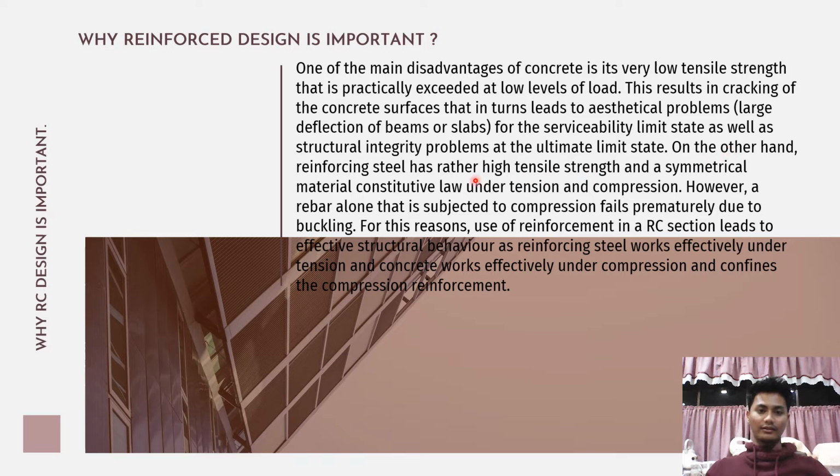On the other hand, reinforcing steel has rather high tensile strength and a symmetrical material constitutive law under tension and compression. However, a rebar alone that is subjected to a compression fails prematurely due to buckling.